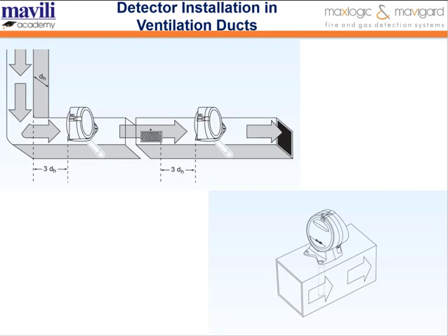The detector should be installed on the straight section following that bend, and the installation distance should be 3 times the width of the air duct. For instance, if the duct width is 2 meters, the detector should be installed approximately 6 meters after the direction change.